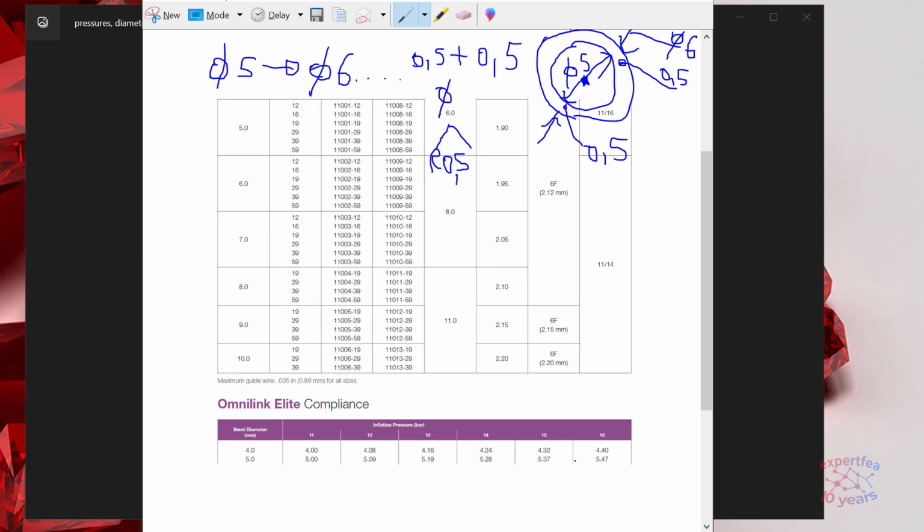And here it shows that if we are going to apply a pressure of, let's say, 16 bar, which is 1.6 megapascal, then we're going to have, let's say, 0.5 dilation, total dilation, which will split on the radius exactly as here, only half of those dimensions, 0.25, 0.25.